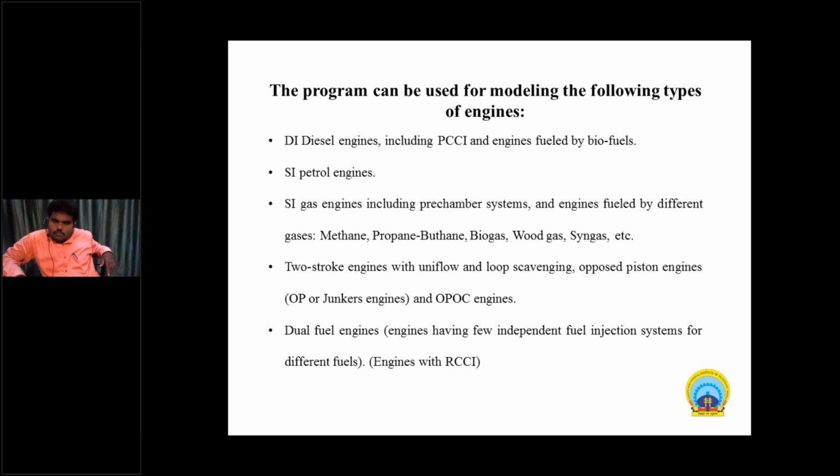And there is good agreement between calculated and experimental heat release rate curves and integral engine data also. So each fuel spray is split into a number of specific zones with different evaporation zones. These zones are formed on the cylinder liner surface and on the cylinder head, and this is also taken into account. So the piston bowl in the modeling process is assumed to have an arbitrary axisymmetric shape. So the combustion model supports central, non-central, and side injection systems.